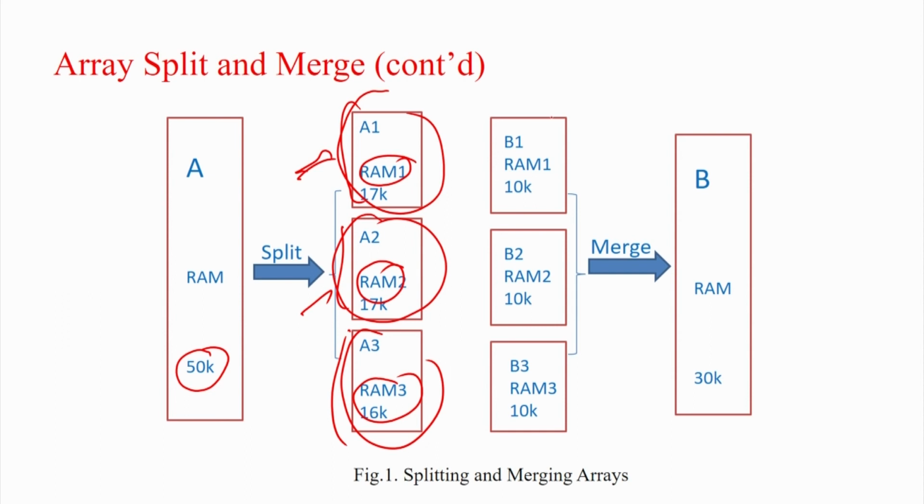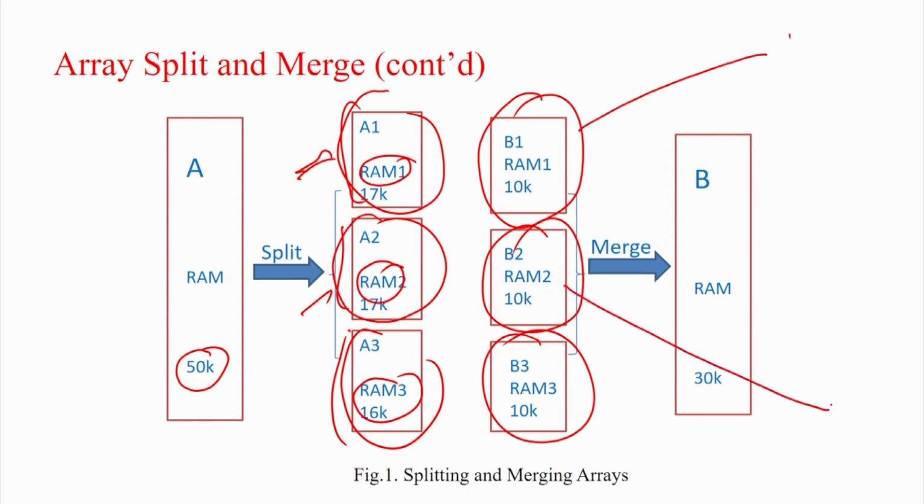Similarly, the other way, if you have a very small array, inferring RAM for them is a waste of resource, right, because your RAM size is 18K, 20K in hardware, and suppose your array is only 1K or 2K. If you do not violate the performance, in the sense that this is accessed very early in the loop and this is accessed very late in the main code, then probably their accesses are non-overlapping. Even if you map them, since they are scheduled in different time steps, their access can be done through the same port.